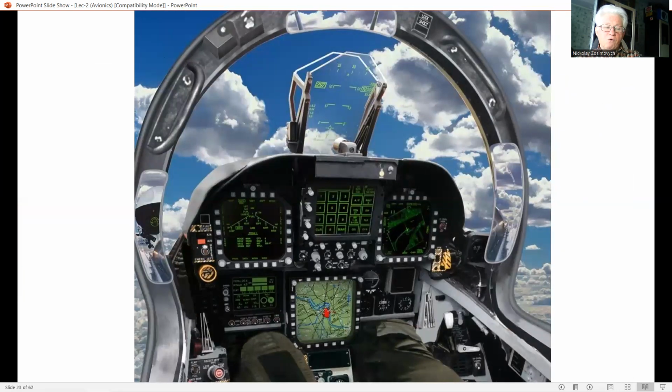The IFOV of a refractive HUD using a combiner with a rugate dielectric coating still suffers from the same limitation and cannot be increased like a holographic HUD. It can nevertheless provide a very competitive solution for applications where a maximum IFOV of up to 20 degrees is acceptable.